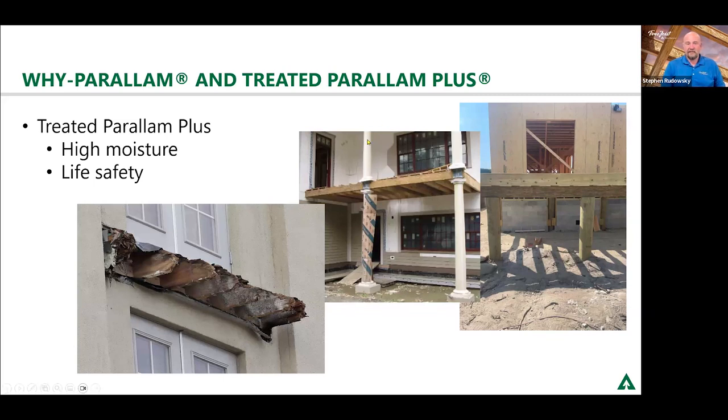Now, if you were to take this and enclose it, so that this was a room above and your walls and your siding came down and went below the area that's needed, this beam wouldn't have to be treated.